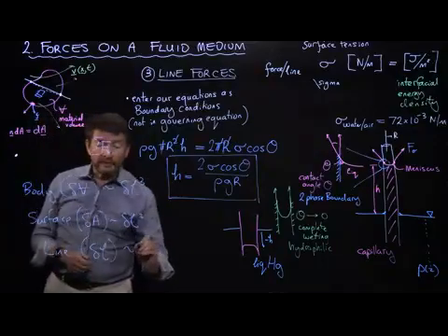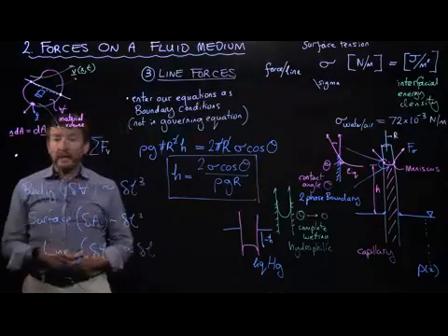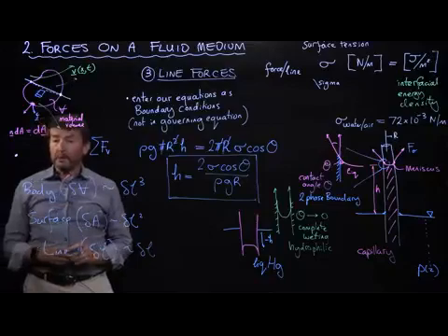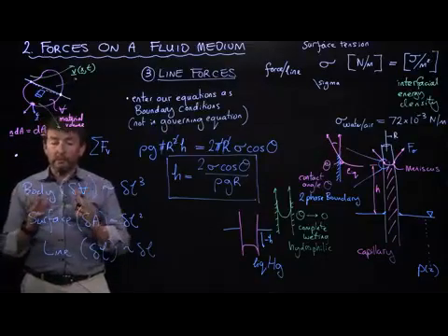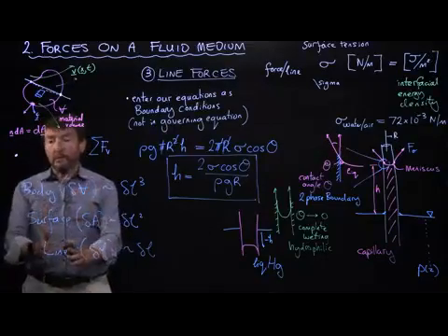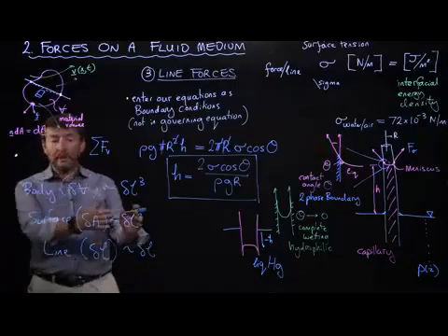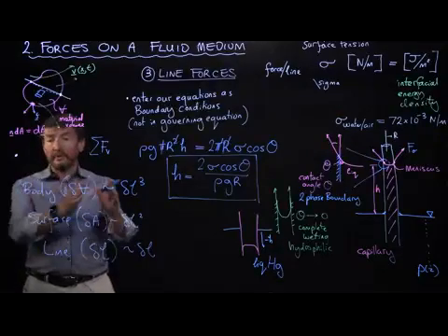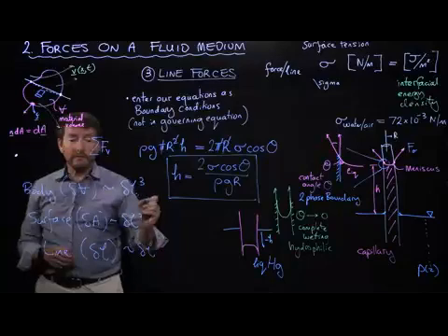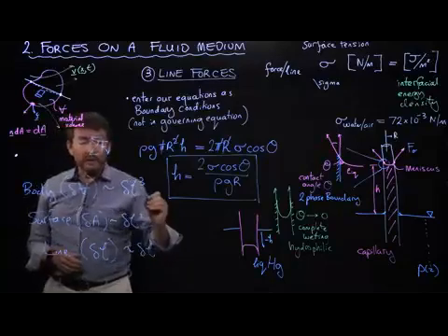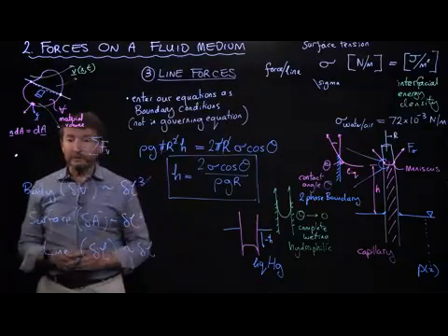And this, of course, is of delta L. And so you can see that as things get smaller and smaller, line forces get smaller, but surface forces get quadratically smaller, and body forces get cubically smaller. So in general, as the world gets smaller, then body forces will become negligible first.